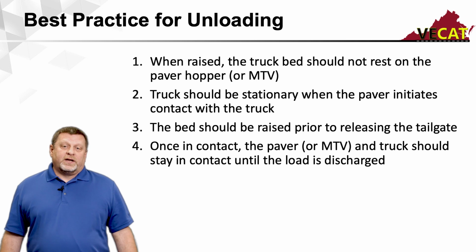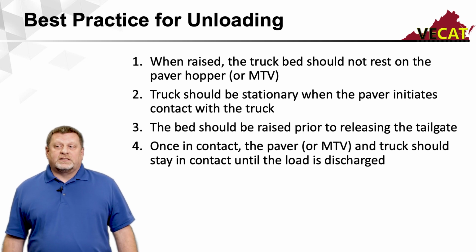And then once you're in contact and once you begin to release this load of mix into your paver hopper or your MTV hopper, it's important that contact be maintained and they stay connected until the entire load is emptied and they've received a signal to move forward and pull off the site.